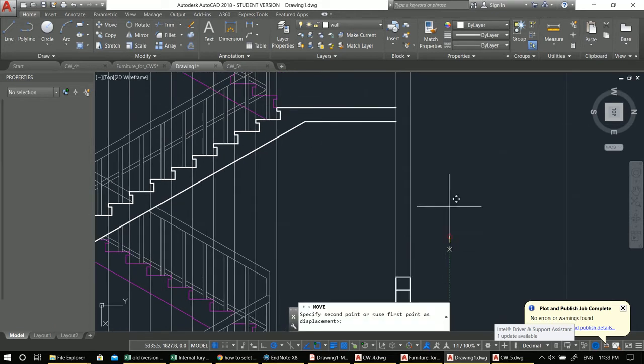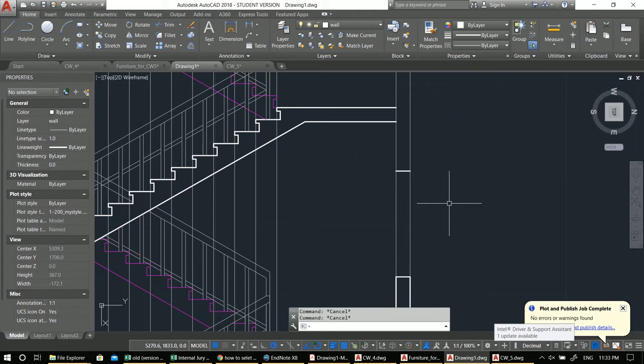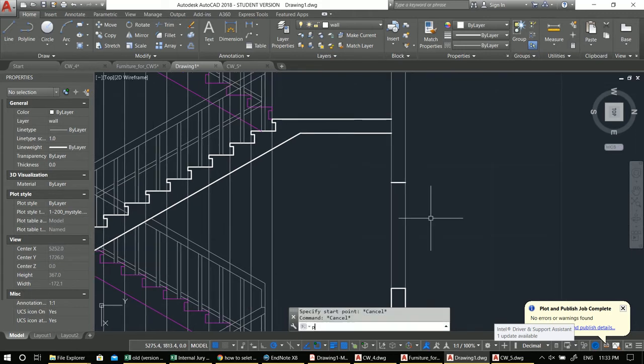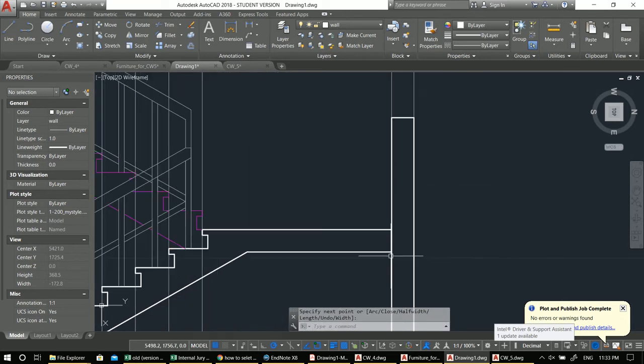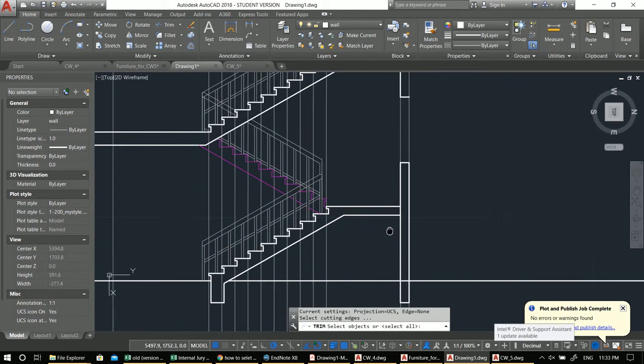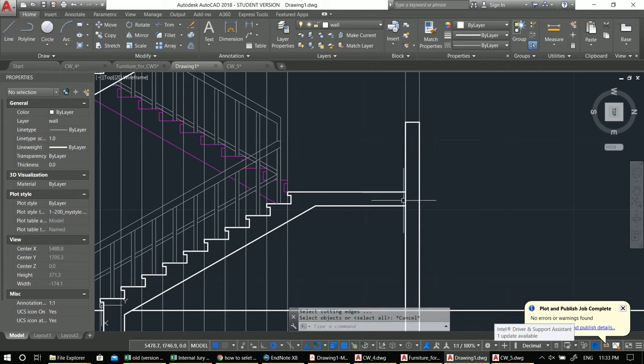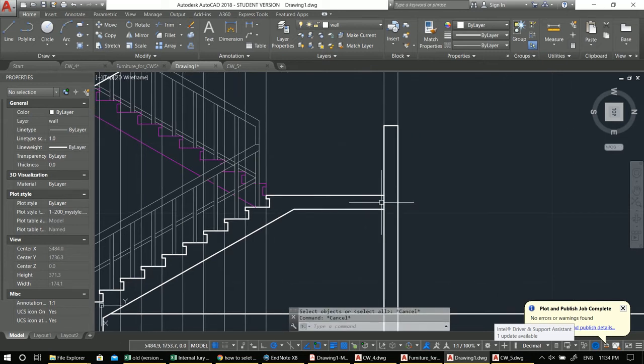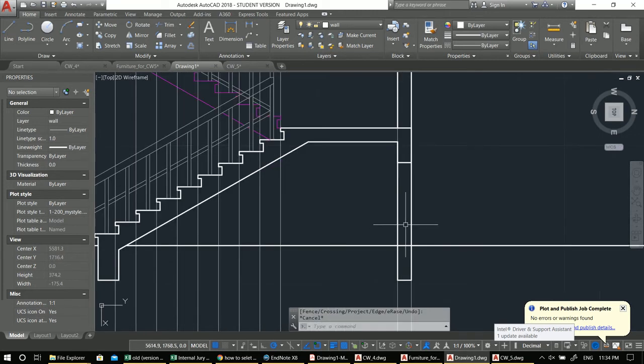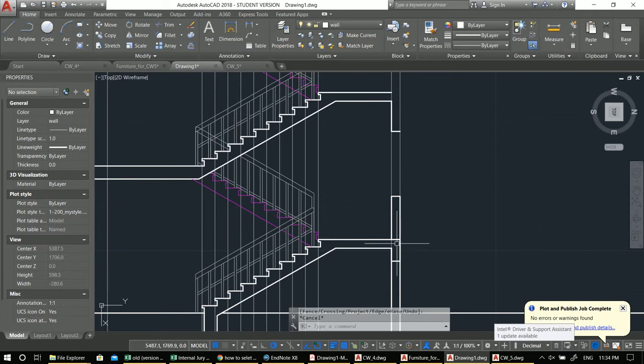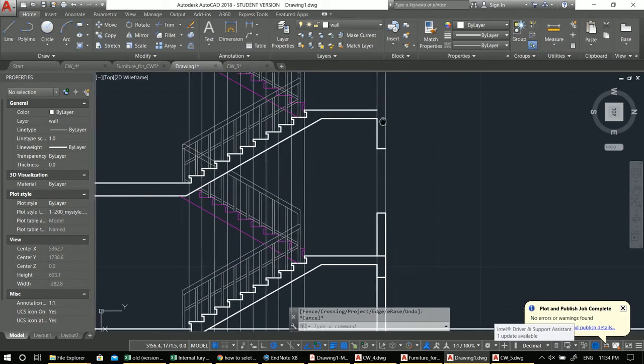So I'm moving this up 150. I'm just drawing the outline of the staircase. If you want to add more details, I'm repeating, this is not a technical drawing course. So here, if you have construction detail, you don't show it like this. You show it something like that, so you'll be able to hatch it easier. Like if you have a 50 centimeter beam for the stair, or the type of construction that you are doing, you do it according to that.